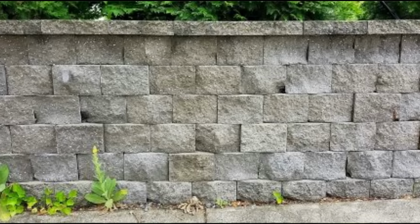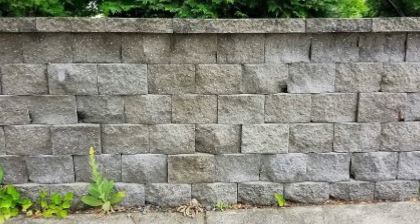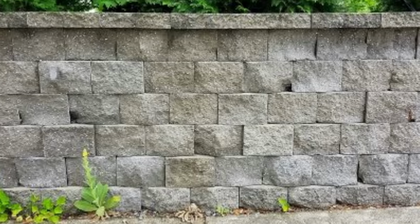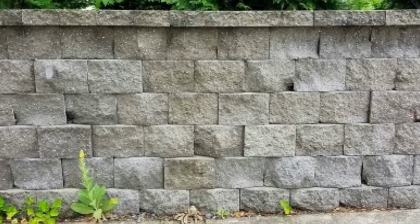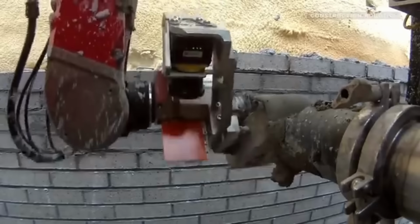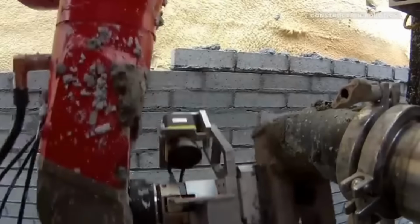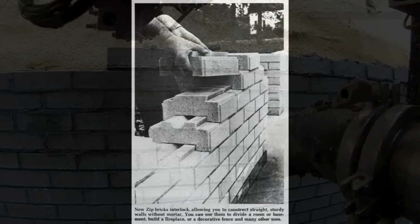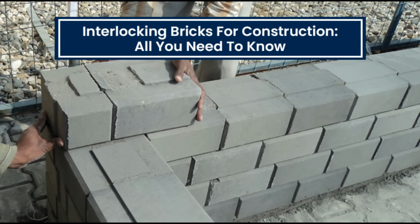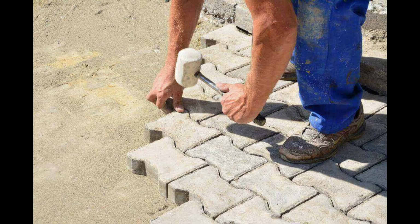Well, anyways, nowadays ashlar type masonry is quite common since we can manufacture standardized bricks and pavers at scale. You've probably seen walls like this, so if we're casting basalt into standardized molds, then this is a viable option. But if this isn't enough, if you really need these bricks to stick together, maybe the lunar monsoon season is really strong in your area, then another option is just to make these units interlocking, which we can do with a number of different geometries, and this could be especially useful for roads and landing pads, which will experience a lot of different forces.